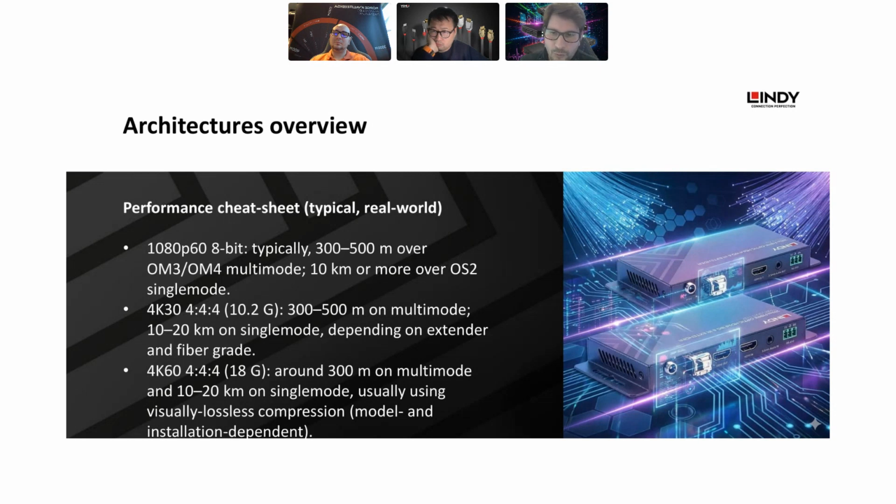If we go further, 10 or 20 kilometers on a single-mode cable, depending on the standard or the fiber. Up to 4K 60 Hz, 4:4:4, with a bandwidth of 18 gigabits, around 300 meters on a multi-mode cable. And as I said before, you can reach 20 kilometers on a single-mode cable, usually using visually lossless compression, depending on the installation and the model that you have chosen.